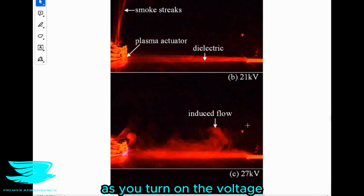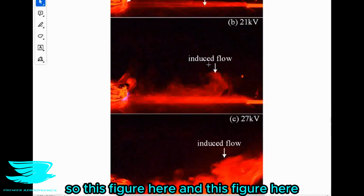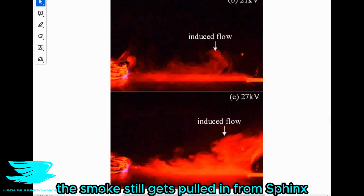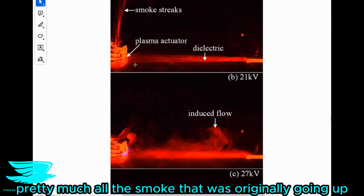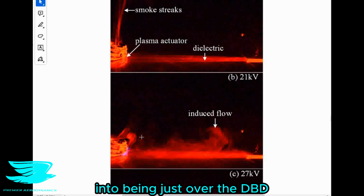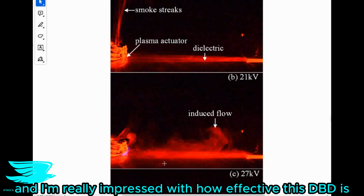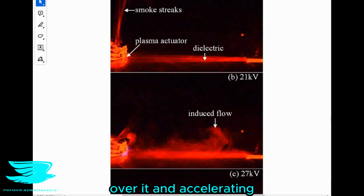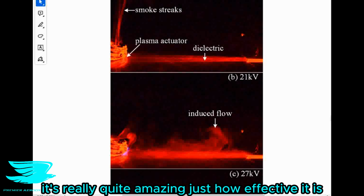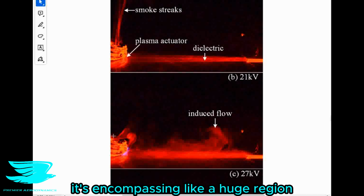Amazingly, as you turn on the voltage, so this figure here and this figure here, the smoke still gets pulled in from being so far away at 21 kilovolts. Pretty much all the smoke that was originally going up gets pulled into being just over the DBD. And I'm really impressed with how effective this DBD is at pulling flow from really far away over it and accelerating it. It's really quite amazing just how effective it is. It's encompassing like a huge region.